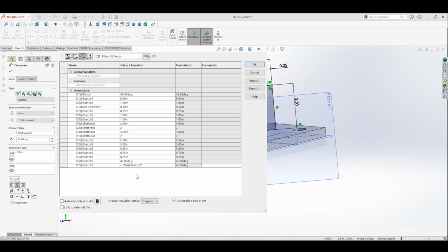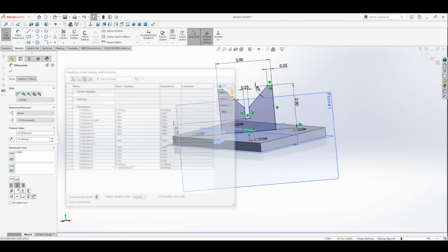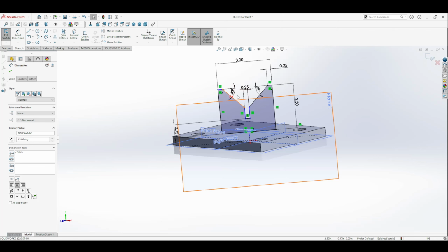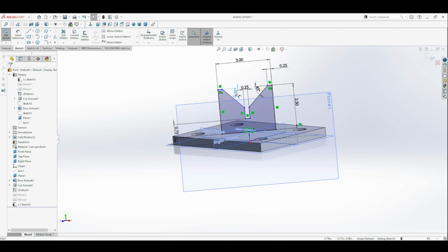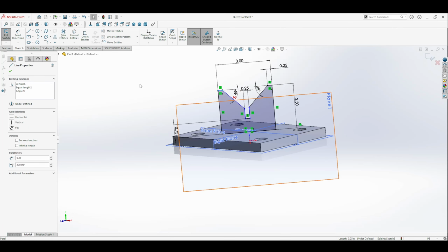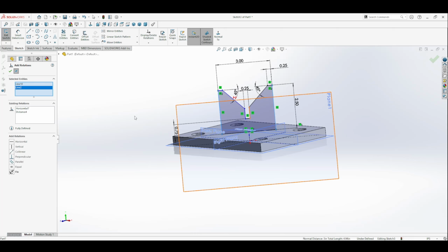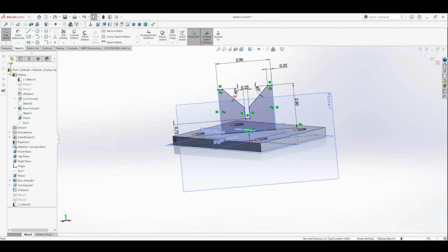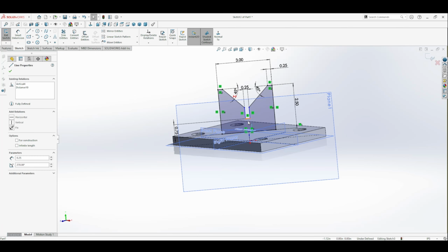So, getting back to this, we've already set this up, so we'll hit OK and give it a second, and you can see here that this angle now has this funny looking summation symbol on it, and that's because they're equal to each other. And the last element that we missed here is that this line right here just has to be equal in length to the other side. We'll just set the two equal, and that should be it. Let's just make sure. There could be something I missed.